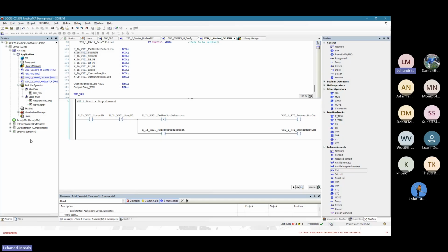But one thing to note, for the HMI, we will be toggling the start and stop push button. So I will need to reset the HMI bits, so the input bits right here, when the other is pressed. So to do this, we'll do the following.